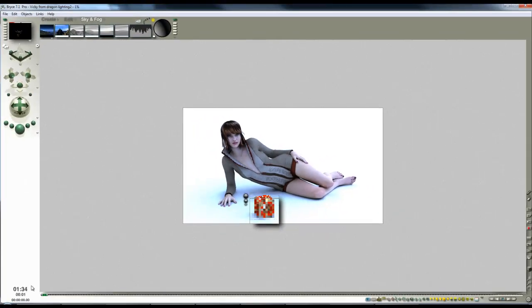But since this is the only bit that requires it, what I can do is utilize the plot render and just render that little bit, and that's going to take 1.5 minutes to pick up the additional effect of the specularity. And we should see when it's done that it's not actually affect the appearance of the rest of the image. There won't be any change in terms of the effect on the ground plane, for example. You're just getting the specular highlight on this cube because of the sun position. In fact, I don't really want the sun there, so I'll stop that, and just re-render that a bit, having moved the sun round slightly and then move the highlight to be more in keeping with the predominant light source from this direction.